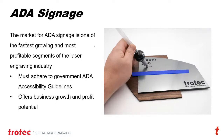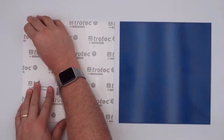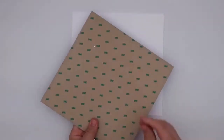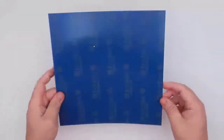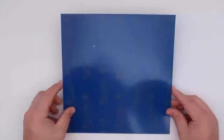and then we're going to do a little more advanced one, a step-by-step multi-dimensional raised letter multi-material sign, and show you the different process. So this is an ADA sign using two different plastics, our ADA Trotec plastics, or TroGlass plastics. I've got a white backing and the ADA blue surface. In this case, the ADA material is at a specific thickness of .020, which is 20 thousandths of an inch, the required thickness for the raised letter lines.